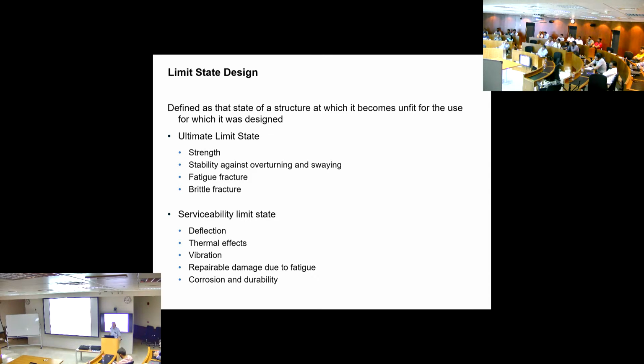Important question: the top sheet. When people walk on the upper sheet, do you consider any support from the rock wool, compressed rock wool below, or is it totally hanging on the CalZip sheets? You can walk on the CalZip sheets, and we don't consider that support. There's a way to walk on them. You don't walk in the pan. You have to walk on the seams. They've been tested for people walking on the sheet.